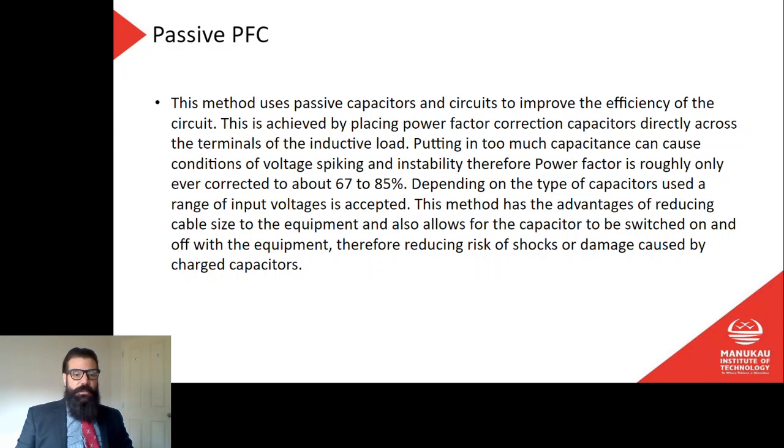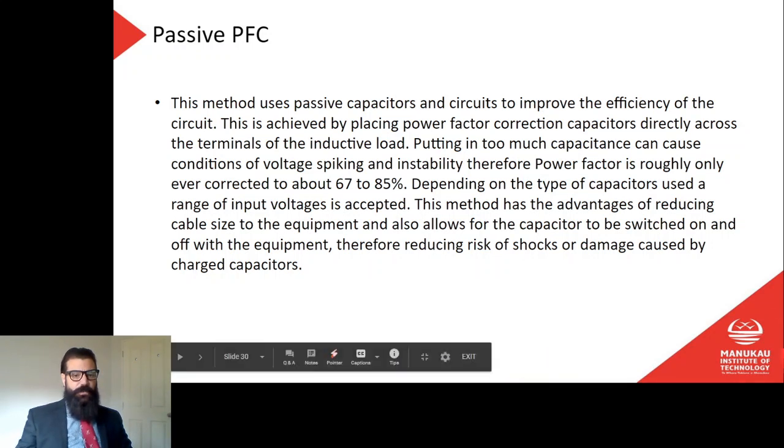Depending on the type of capacitors used, a range of input voltages is accepted. This method has the advantage of reducing the cable size to the equipment and also allows for the capacitor to be switched on and off with the equipment, therefore reducing risk of shocks or damage caused by charged capacitors. So we're putting the capacitor at the load.